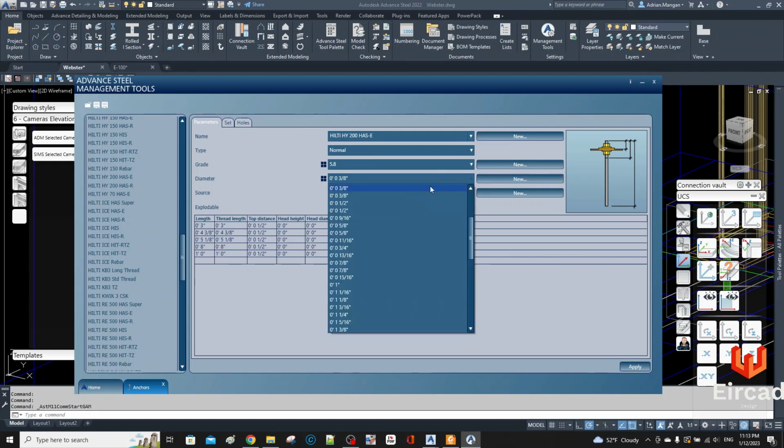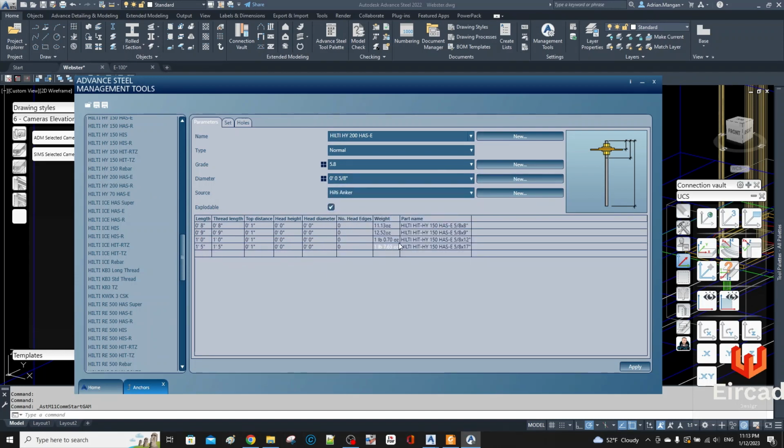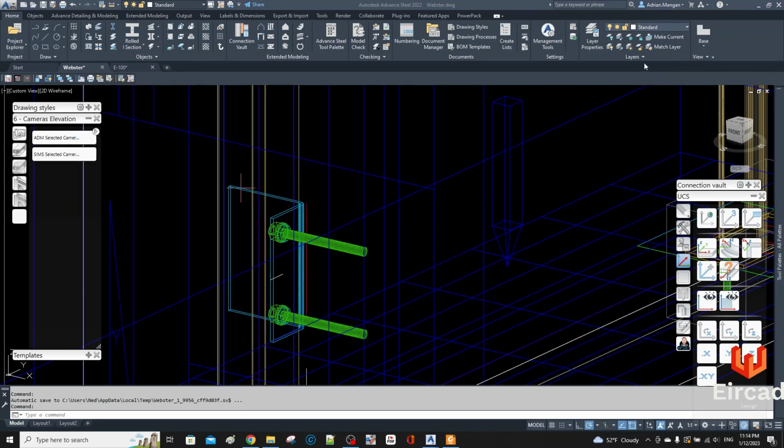That has E5/8, so you can see where they're wrong. So that's why it's coming up wrong. So go in here and change this to 200. It's supposed to match the other one. And I never changed them because I usually don't use 5/8 bolts. So I was going to say a good excuse to change it, but generally I don't copy from my laptop back to my desktop. Apply them, close that, and then apply these again.